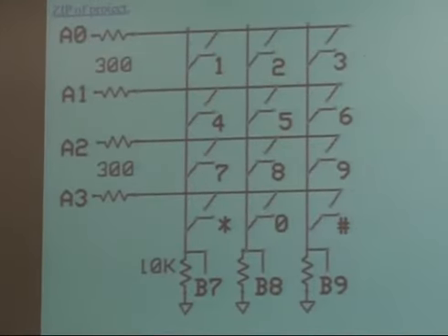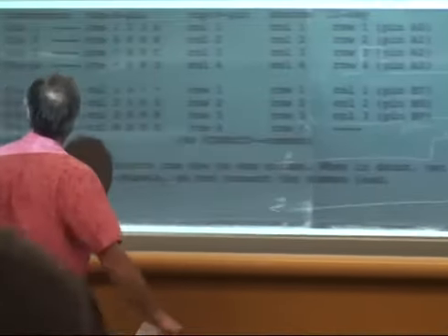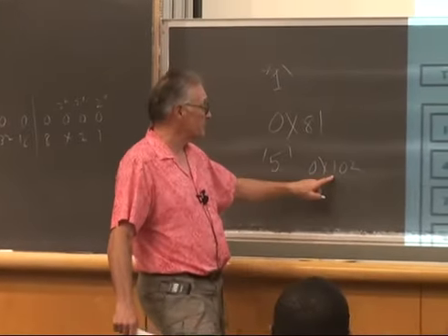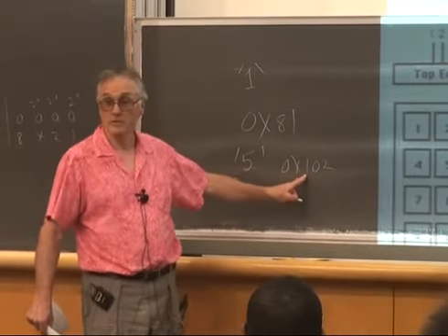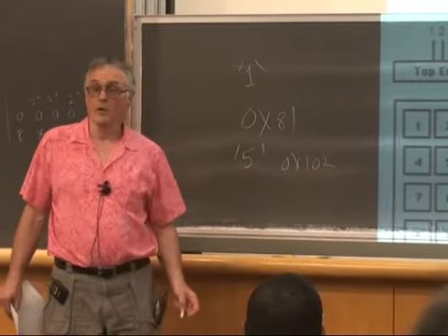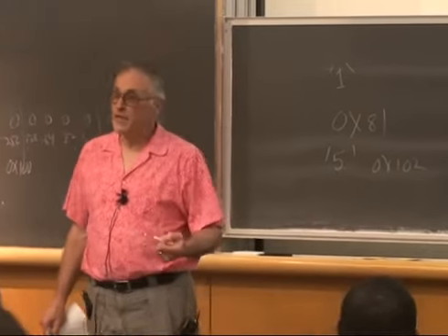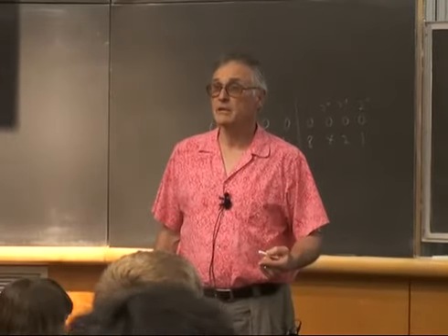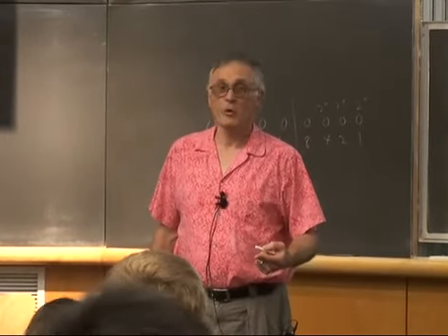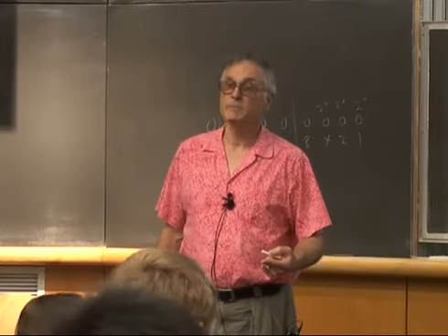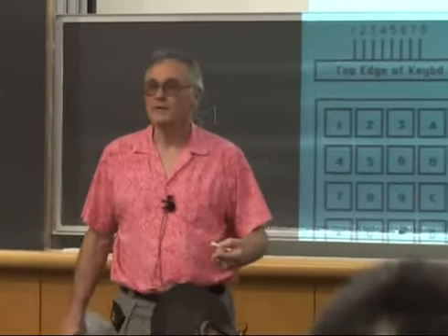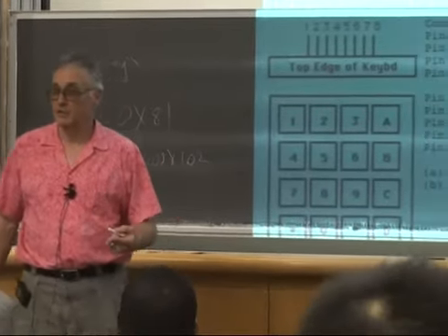So A1 is set, and B8 is set, so the high order digits must be hexadecimal 100. So we're going to scan the keypad until we get a non-zero B result, and OR together the A and B ports. And that'll be the scan code. The next step will be a table lookup to convert that to something useful like a digit number.